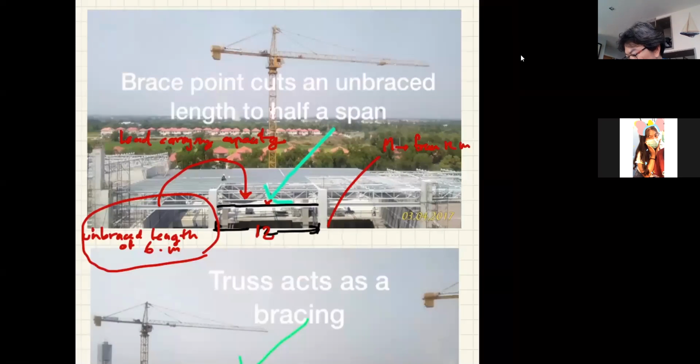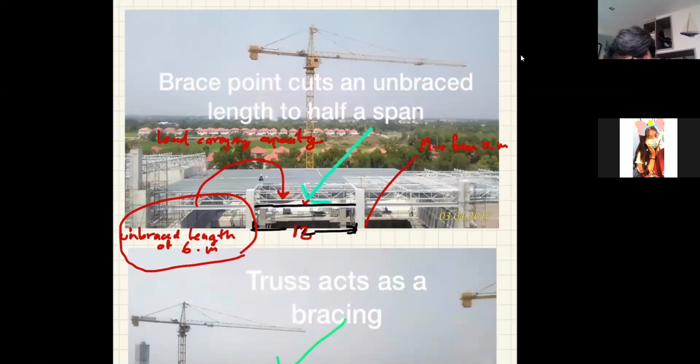So let's come back here. You see, this point can be considered the bracing because this truss is coming down on the beam, and look at the system of the truss. This should be strong enough to prevent the movement of the beam at that particular point. That is why this point is considered a braced point of the beam, and the unbraced length in terms of the design becomes half of the entire length of the beam, or 6 meters.